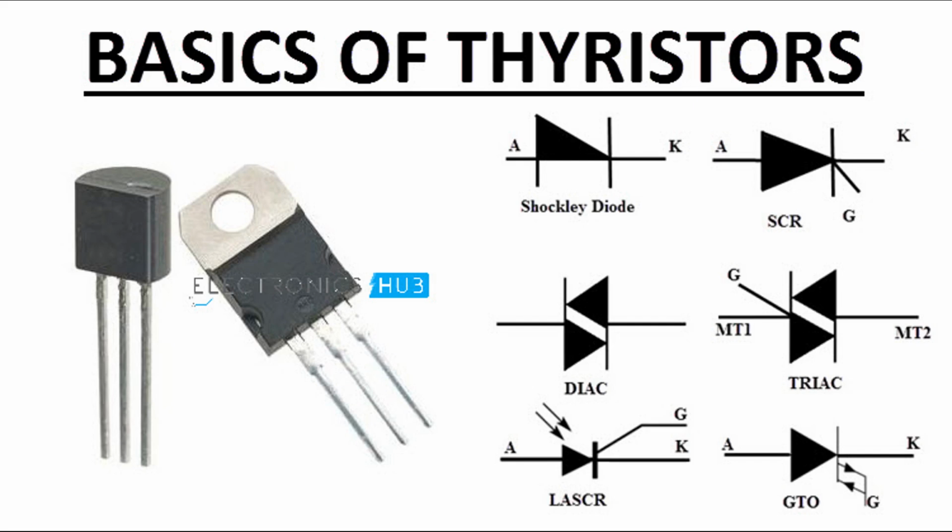the off state. Key characteristics. Bidirectional conduction. Can conduct current in both directions once the breakover voltage is exceeded. Breakover voltage, a characteristic voltage threshold above which the diac conducts. This is typically around 30-50 V for most diacs. Switching behavior provides a sharp transition from the off state to the on state, making it useful for triggering other devices like triacs. Applications. Triggering triacs.